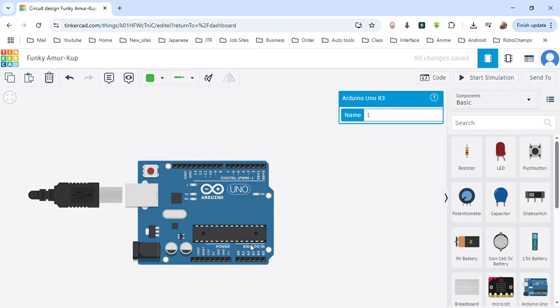If we jump here, this is analog. In analog we have only input. Something like a fan regulator, where we change positions with more than two positions, let's say 0, 1, 2, 3, 4, 5, rather than just on and off. Whatever comes as an input that is analog, something like brightness or different switches which have more than two positions. Those switches or sensors can be connected here as analog in. This is A0 to A5. Here you see this is analog reference and this is ground. We already know analog reference is similar to the positive, but for the analog. And here, we already know this is the input.